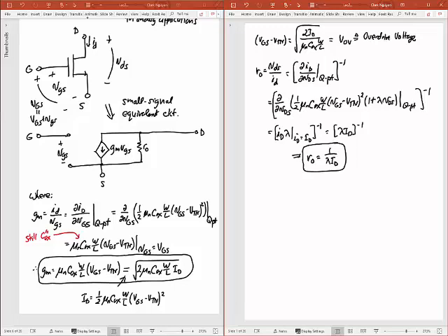Okay, and so one more thing though, so that I should say that's not the complete model. So MOS throws another kink into the model here that makes it a little more difficult than bipolar in some instances for small signal. And so what we'll find is bipolar is very easy DC wise, DC bias wise, but it's a little more difficult small signal wise. MOS is very easy small signal wise. It's more difficult getting a DC bias for MOS. So you'll see that as we do more lectures here.